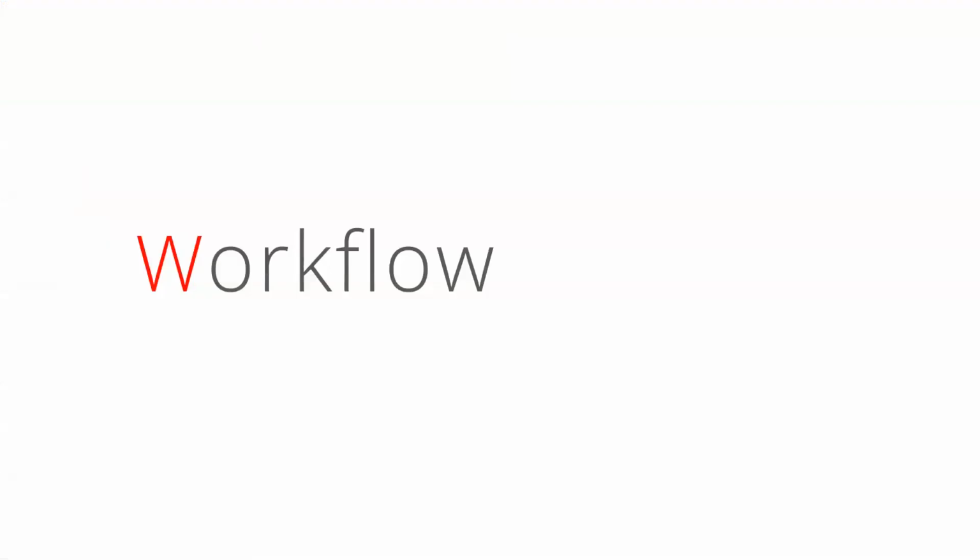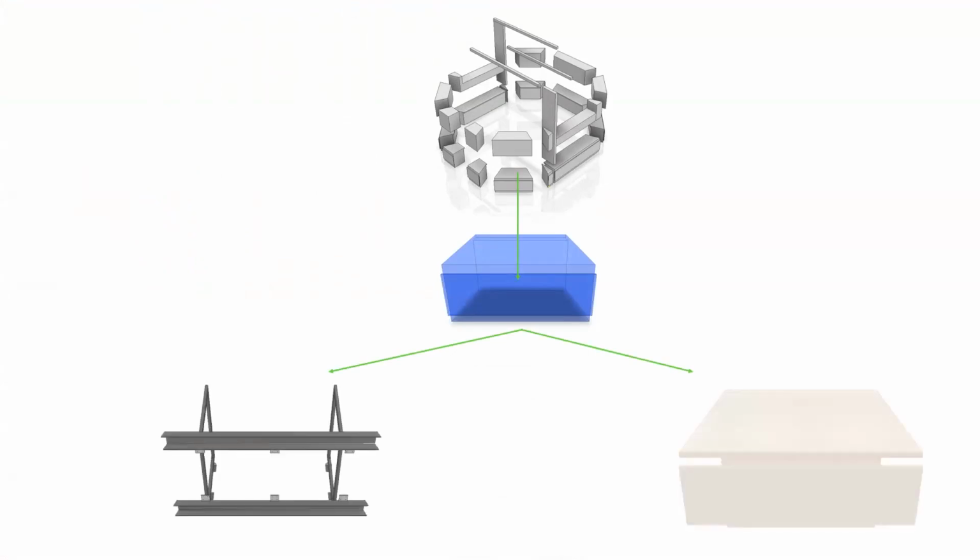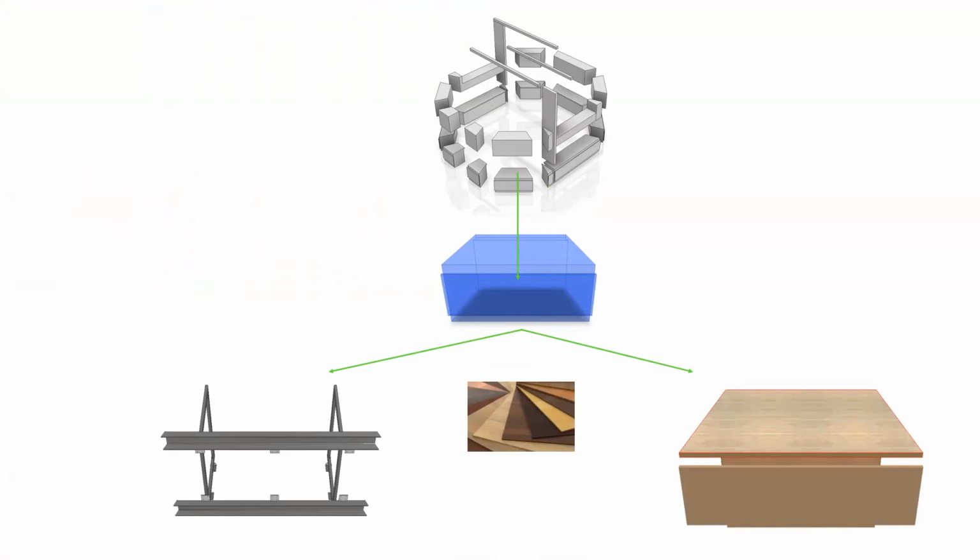Okay, so now let me just show you the workflow once again to make things clear. We started from a simple skeleton concept, then I split this concept into blocks. Then I took each of the blocks separately, split the metal part from the wooden part and did some refinement. I set the materials, the oversizes, and grain direction for the wooden part, and just set the materials for the metal frame members. Also, I applied some ironmongery, all the hardware, to fix the things together.